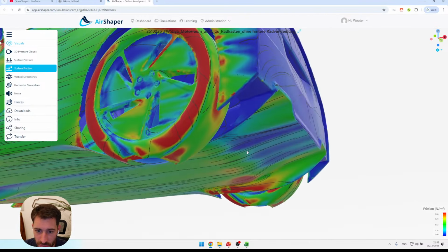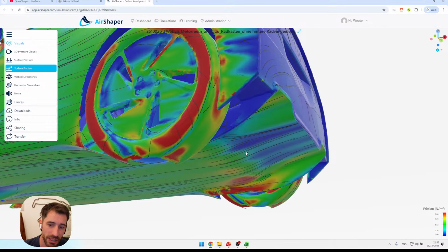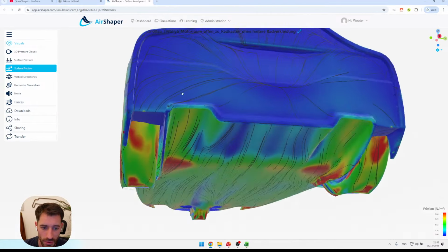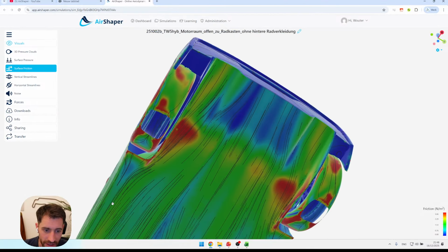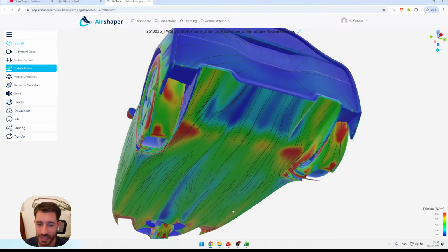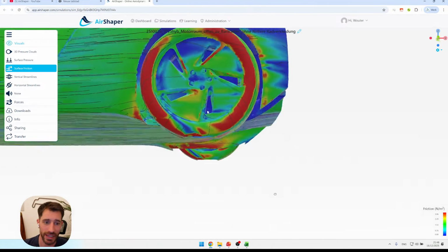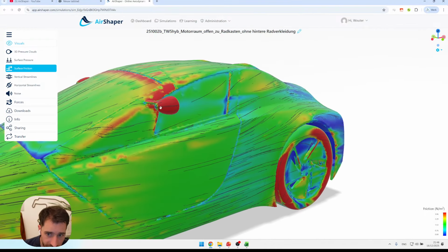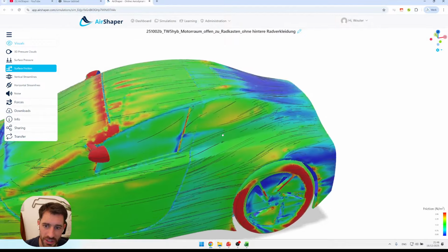And then the central part, which is sitting right below the hard points of the chassis and covering the trailer hitch, again featuring this S curve. So one complete area connecting the air deflector, the sidewall, the diffuser, the central part, the trailer hitch, and so on into one nice organic shape, which is really, really nice to see. We have very limited flow separation in other areas.